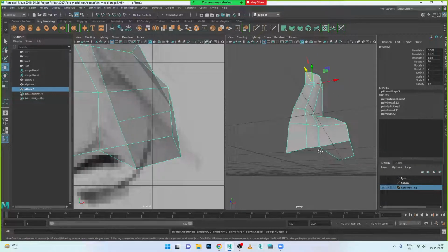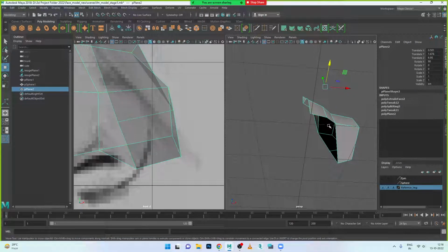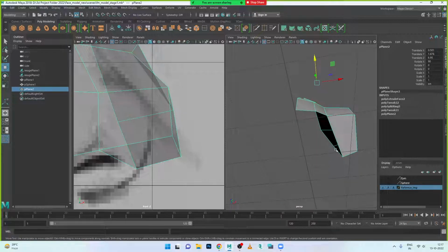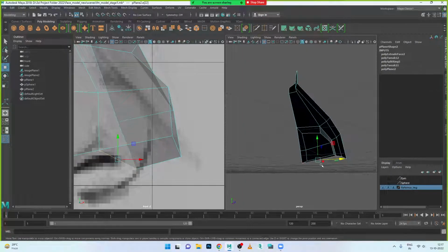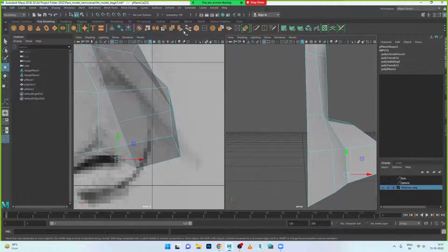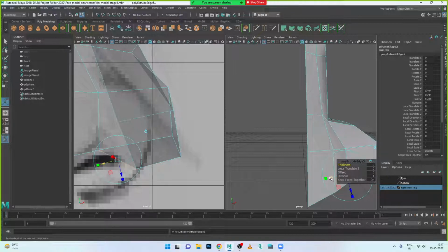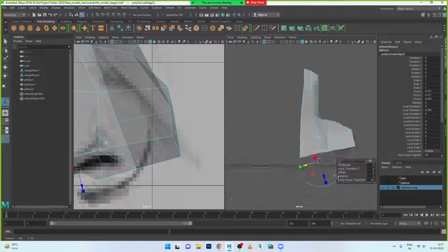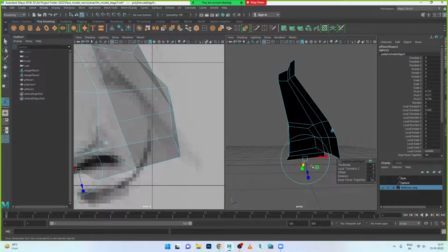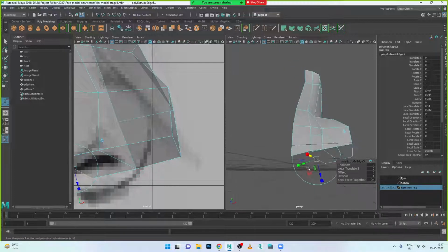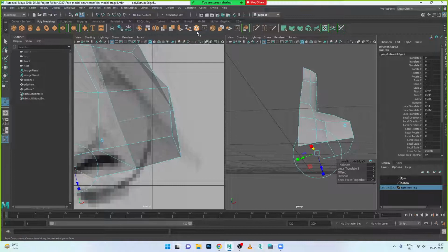Press the 1 key first. Why? Because now this area has to be extended. Either you extend this area down or this area towards the left side. So what to do? Select this one and try to use the edge on this one and try to move this left side once. So use the extrude option. Okay, try to move this left side now and see which area you want. First of all, it should be adjusted here. So move this towards left side, a little front area to balance this one. One more edge we need on this side, one more extrude we need. So use one more extrude and take it back again this one.